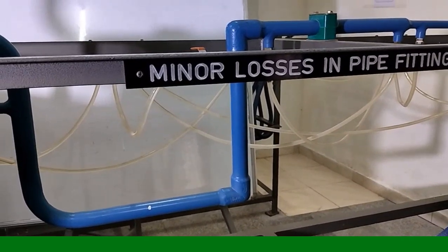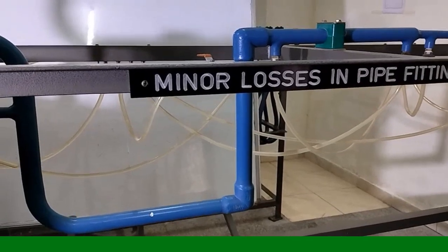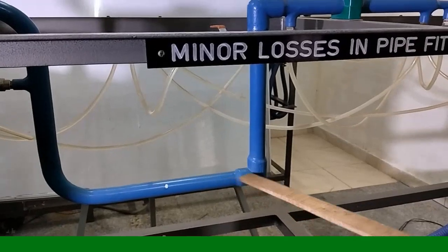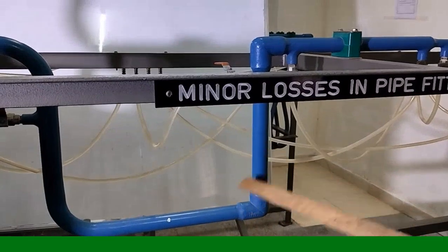Suppose when the fluid is moving like that, suddenly some fittings come. What will happen at that time? The velocity of the fluid will change, the direction will change, and at that time also losses will happen. That one we call the minor losses. Minor losses mean the losses due to the fittings,